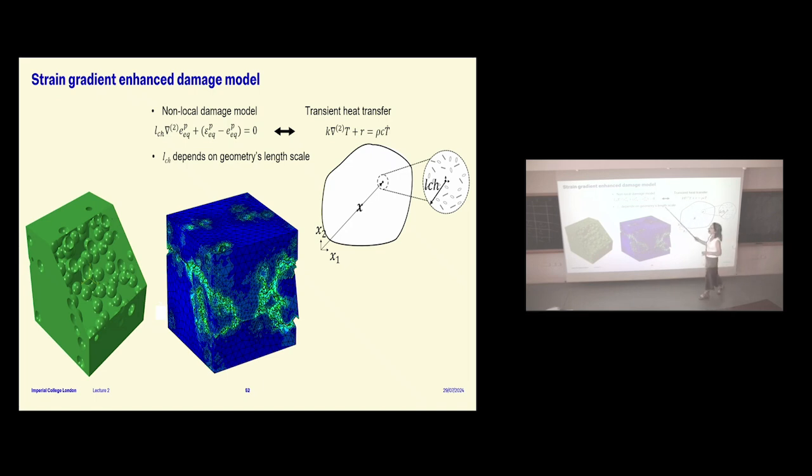And the way to do that, I mean, the way we use damage models in the literature: you need to solve this differential equation. This epsilon was the local strain, where I had all those damage equations. You introduce this E, for non-local strain, and you need to solve this differential equation. Now, the fortunate thing is that this equation and that equation look very similar. This is the transient heat transfer equation, where if you put T, you can put the non-local strain. So there are actually subroutines in Abaqus to solve this problem. All you have to do is change the variables to think that these temperatures are actually your non-local strains. And it works quite well. Lots of people did that.